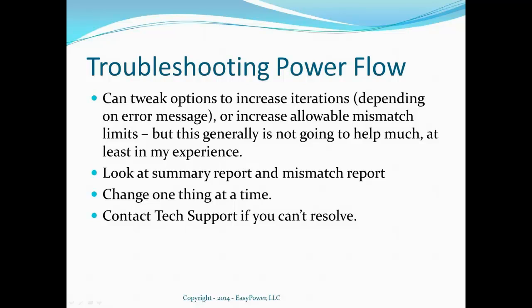Question on wind turbines. How do you model wind generators providing power to the utility? Those are typically going to be like a PV source. It depends on the type of generator. If these are like the type 4, they're full inverters, and it's going to look like an inverter to the system, so you need to model it that way. If it's an induction machine with some kind of power factor control, you're going to want to model it as an induction generator. So it's kind of a special case, but they can be modeled depending on the type of wind turbine. There's quite a few different options there.